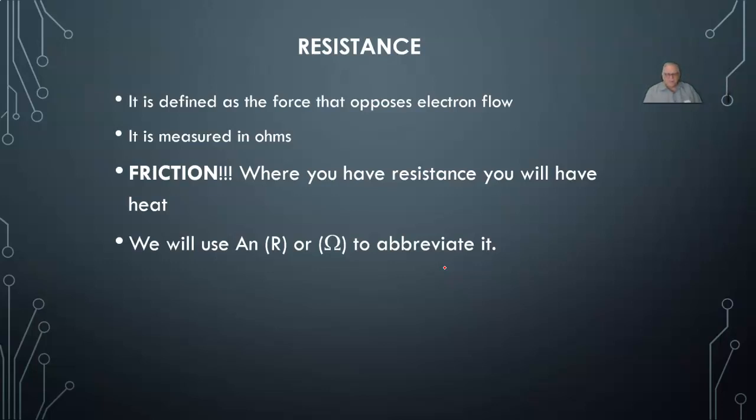Take an incandescent light bulb, turn it on, wait a few seconds, and then grab a hold of it with your fingers. You probably won't do it a second time because it gets really hot. The best definition that I've heard for an incandescent light bulb is a heater that happens to give off light. They're only about 20% efficient, meaning that 80% of the energy that they consume is heat. When you start going to some of these advanced electrical classes, you'll find guys using an infrared camera to find resistances on a circuit because it'll show up as being warm or hot.